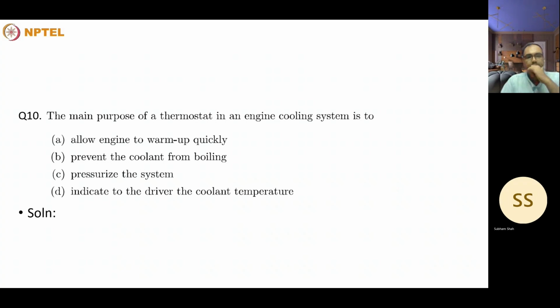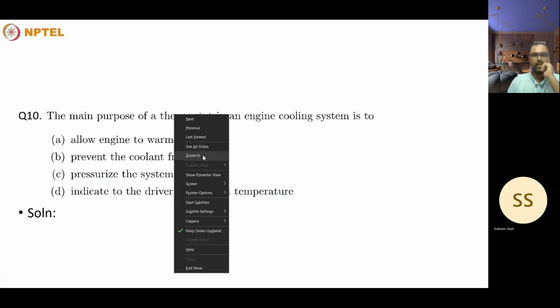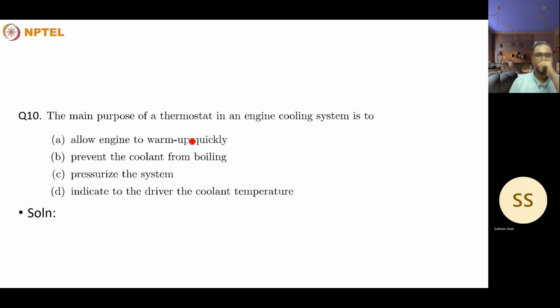It will allow the temperature to be maintained at a particular temperature, and it reaches there quickly. So basically, the main purpose of a thermostat in an engine cooling system is to warm up the engine quickly.